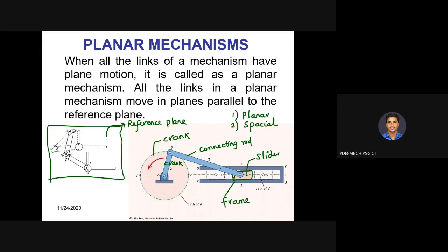Okay, so your connecting rod is connected to the slider, and the slider is going to make reciprocating motion inside the cylinder. If you assume it is an IC engine, you will have an inlet valve and an exhaust valve, so that fuel comes in, compression happens, and power is obtained. Then the power will be transmitted from the slider. That power acts on the slider. The slider is connected to the connecting rod, which is connected to the crank, so the crank will be rotating. So the output you are going to extract here.